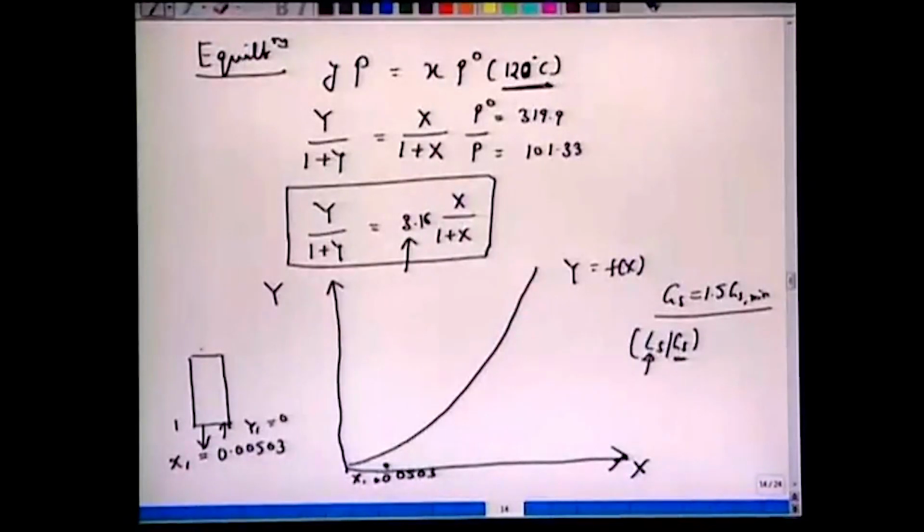We know the concentration here. Now this is x2. Okay, this x2 is 0.119. This concentration is the same as the concentration of the spent liquor from the column 1 absorption column. So we can mark this x2 as 0.119. Just compare again. Earlier we used to mark here y2 because that was the absorption column, that was the condition given to us.